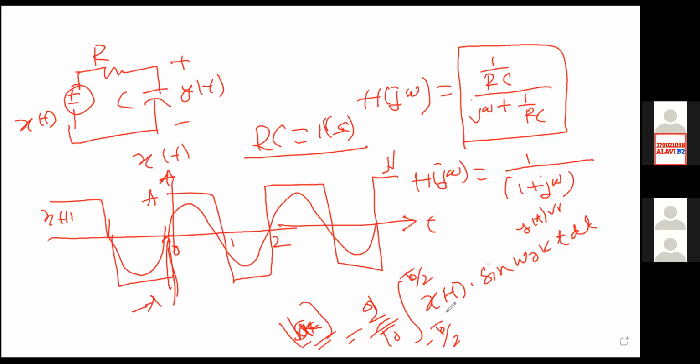What does this operation actually mean? Is it not a filtering type, a comparison type operation? For example, you have x(t) and a sinusoid whose fundamental frequencies are known to you. If these two signals are very similar, then you will get the integral. If they are dissimilar, you will not get a value of the integral. That will tell you at which frequencies you get the maximum value of this integral, giving the value of that k, and that is the harmonic amplitude present in your system.